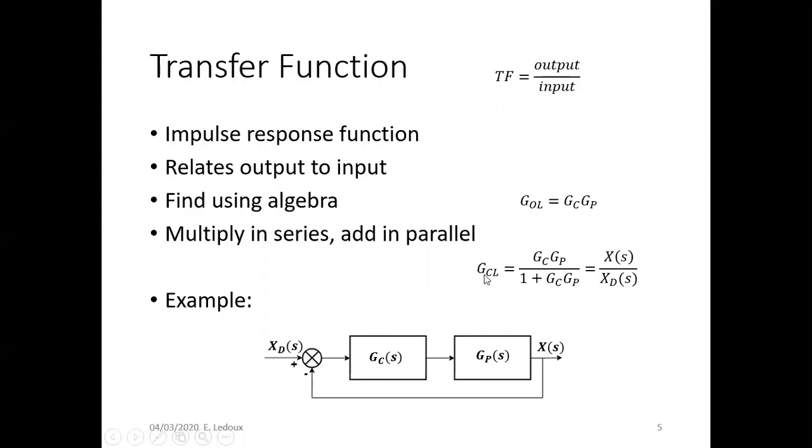So to get the closed loop, it's this formula, and I worked it out in the notes, they're on D2L, called Chapter 6 Controls Notes. That shows the algebra of how I got this formula. And this system is called negative unity feedback because it takes the output and it doesn't do anything to it. There's no change from that output until it goes in here. So that's where the unity comes from, and then the negative sign is right there. So negative unity feedback is when there's no transfer function box down here.